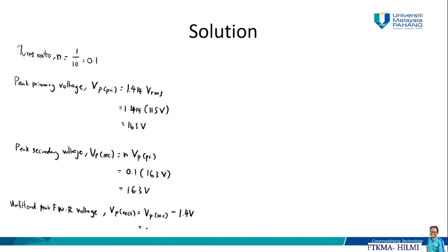So the answer is 14.9 volt, 16.3 minus 1.4 volt. So the frequency F is equal to 120 Hertz. We obtain this from doubling, 2 times 60 Hertz, the input frequency.